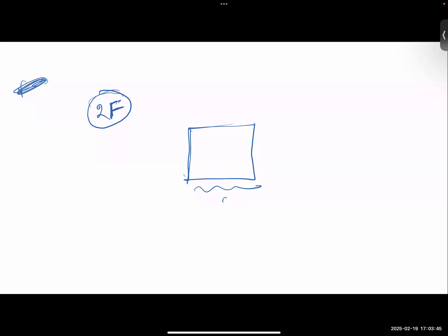Okay, so keeping that in mind, if F is half of minimum feature size, what will be the minimum feature size? That will be 2F. For some reason, industry folks always prefer representing the minimum feature size in this form instead of putting F to be the feature size. So F is half of the feature size, and 2F is the minimum dimension that you create in a technology. When you create some pattern in a silicon wafer, the minimum X dimension that you can have is 2F, because 2F is your minimum feature size. And the minimum Y dimension is 2F again. So what is the minimum area? The minimum possible area would be 4F square.